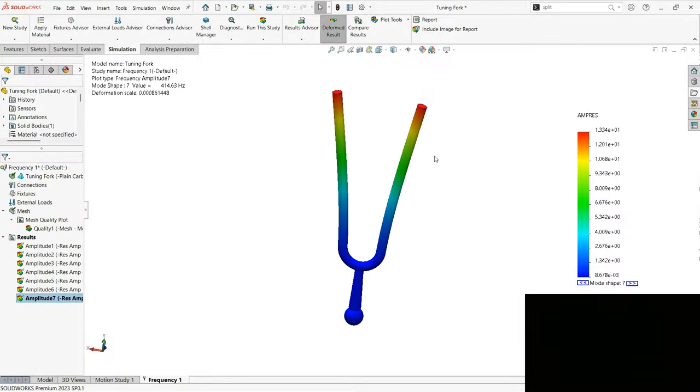Okay. So what is the advantage of doing the modal analysis? The very important thing is, first, whether your model assembly, if you have one, is properly assembled or not, you can check it there. And the second thing is you can check the resonant frequency of the model, so that if other components are meeting the same resonant frequency, definitely catastrophic failure will happen. But some components might work with the resonant frequency also, that you need to keep in mind and try to check the model.